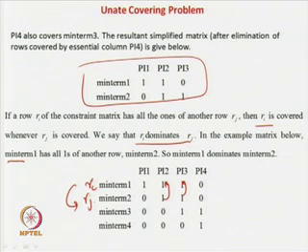Now, in this case what we can do is simply remove the dominating row. Now, see interestingly what will happen, you just eliminate it. The dominating row, you should remember, has more ones than the row being dominated. So, if you remove it, somehow you have to select min term 2, that is obvious.